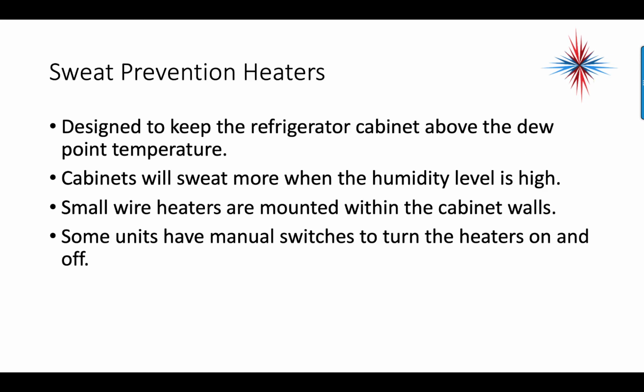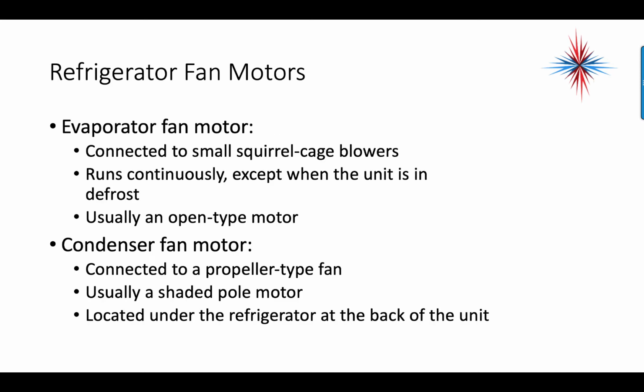Sweat prevention heaters are designed to keep the refrigerator cabinet above the dew point temperature. Cabinets will sweat more when the humidity level is high. Small wire heaters are mounted within the cabinet walls. Some units have manual switches to turn the heaters on and off.